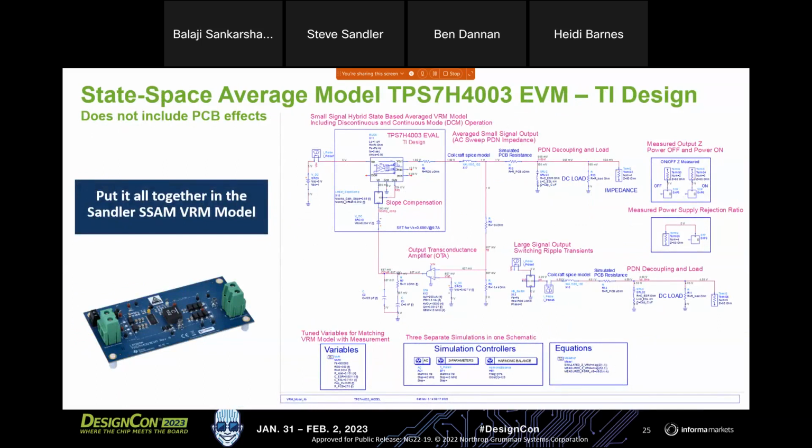Okay, so we have our feedback loop set in here. We got a SPICE model for our inductor. We got our plant parameters for RI and VRAMP. We got our gain settings now for our error amplifier. We have a bulk cap model for all the caps on our PDN, and we're set, right? So let's push the button and hit simulate and look at our results.